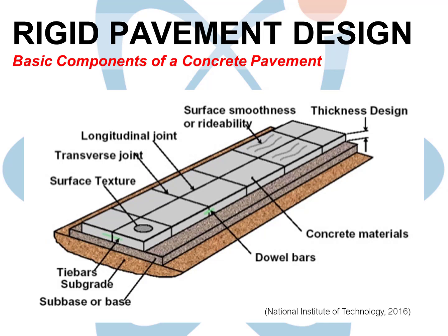In the old days, concrete pavements were placed without reinforcement and without any attention to joints. That was okay back then because traffic counts were much lower and vehicle weights and speeds were much less. Even today, with modern pavement design, due to increases in traffic and vehicle weight and speed, even newer pavements experience joint failure due to overloading causing the bump, bump, bump that you feel.